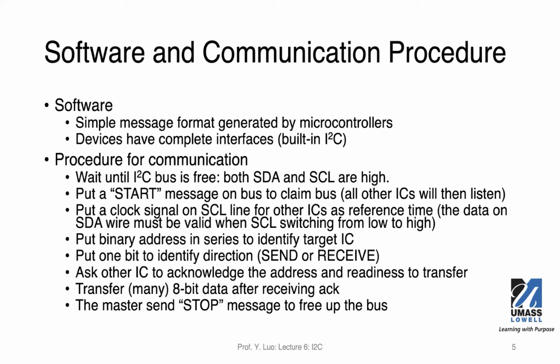We will see timing diagrams later, illustrating how the two wires transfer data and address values. But most of the time, you don't have to write software to generate individual clock signals. Rather, you will use the control registers or other registers of the I2C device to send necessary information out or receive data back.